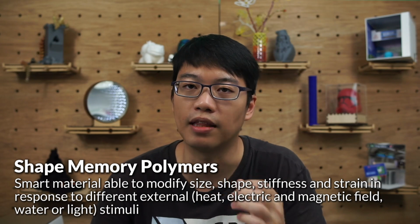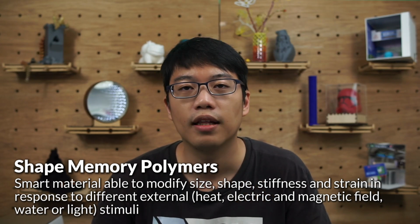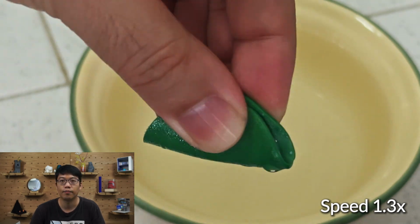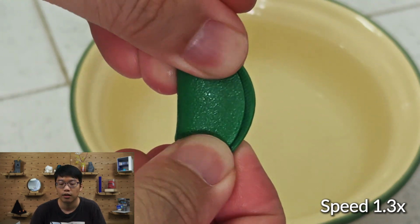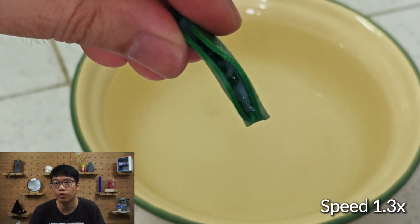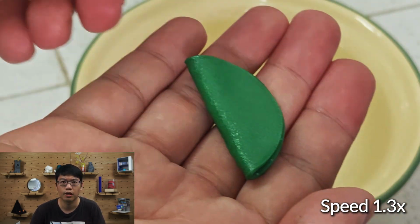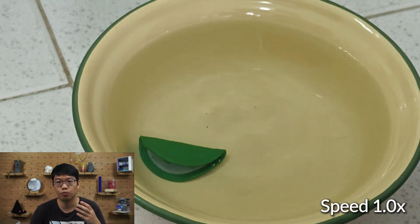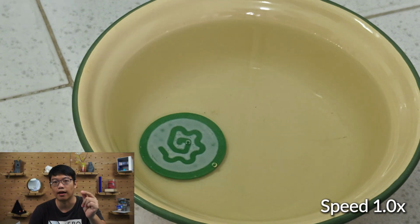The key to this is the nature of PLA. PLA is one of the many shape memory polymers or plastics that is easily available. Like memory foam, it can be stretched or compressed while still remembering its shape. We can see this effect here. We can heat up this thin print and then scrunch it up while it's still malleable and hot. Then we let it cool, and now it's rigid and stays scrunched up. However, if we want to get it back to its original shape, all we have to do is reheat it and it'll simply pop back into place.